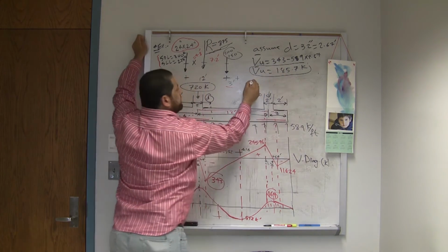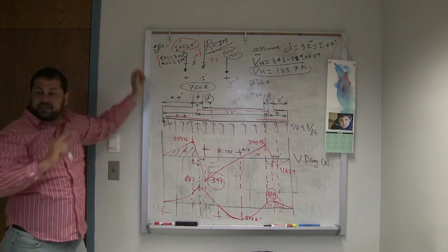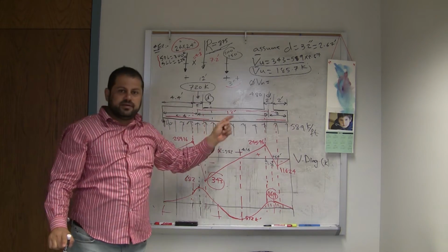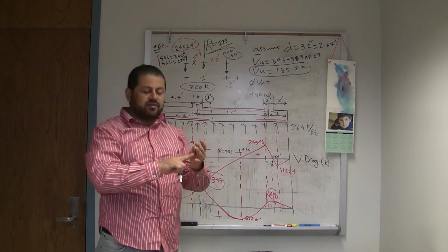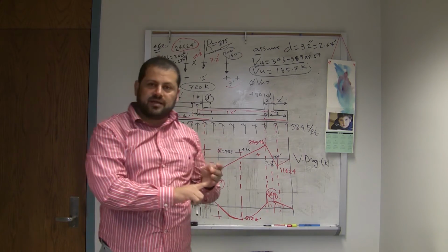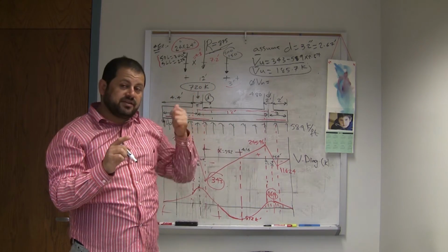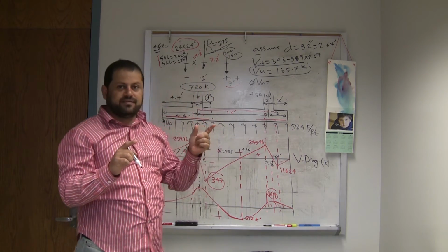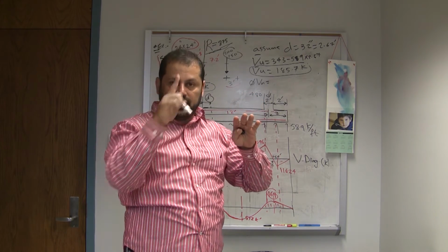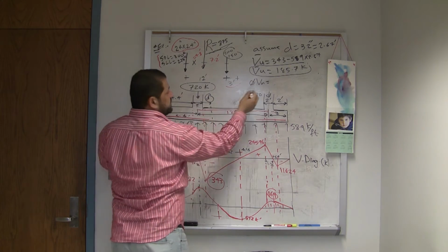Now what's V bar VN? This is a beam shear, not punching. V bar VN equals phi 0.75 times 2 square root of f prime c times B D. For punching it is different: it's phi, which is 0.75, times 4 square root of f prime c times B naught D, and that B naught is the perimeter for the punching.